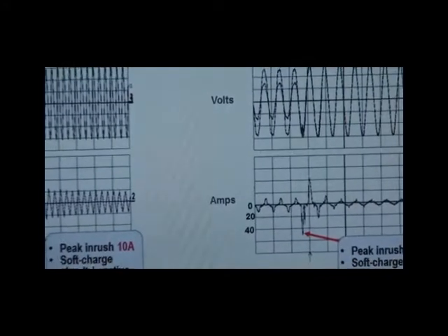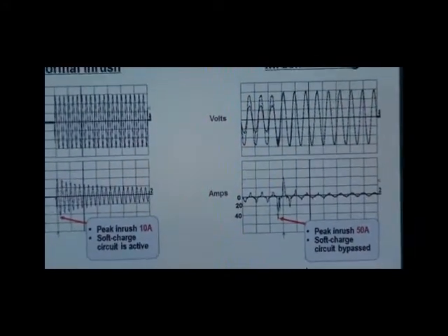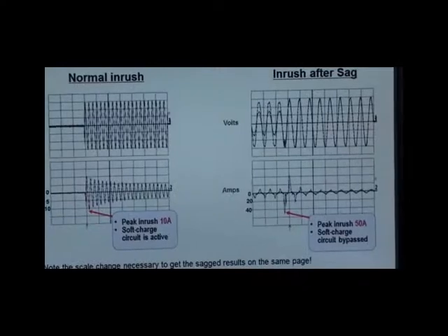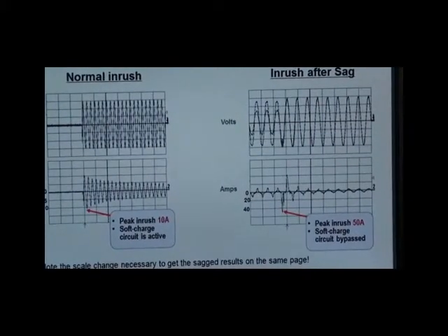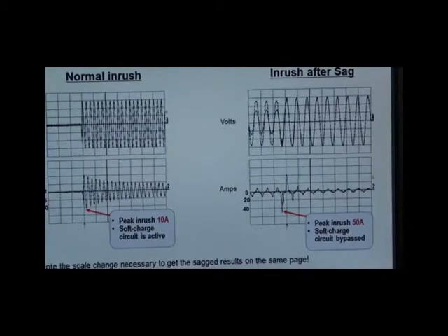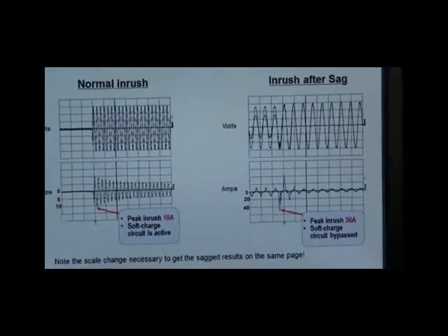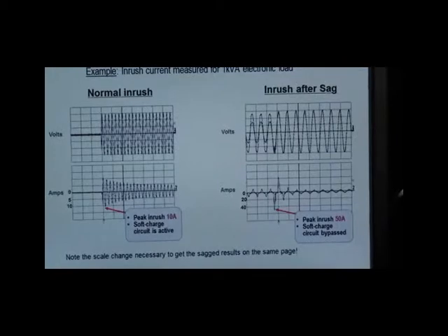This is going to stress the components in that power supply, and if it turns out that that power supply was engaged at the moment in time that sag happened, it's probably going to burn it right up. And the damage will look like you had a spike or a hit by lightning, because the front end of that power supply is going to be fried. What people won't recognize is that it probably was the squirrel down the street that died that caused that voltage sag that just took out that drive or that power supply.